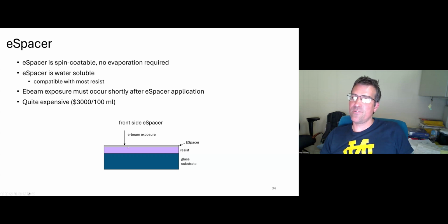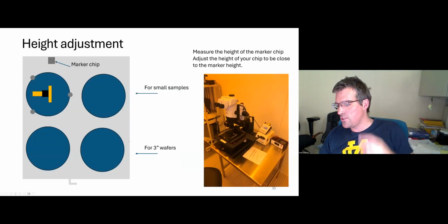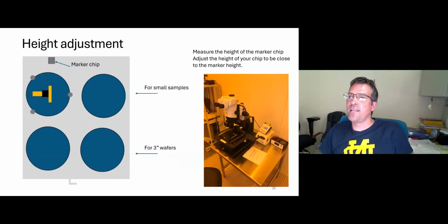So you can consider this one if you have a quartz or a glass substrate, and you are doing a lot of this exposure, and you have real charging issues, then probably it's worth it to invest in e-spacer. Now, I want to finish with two tips and tricks that most new users have issues